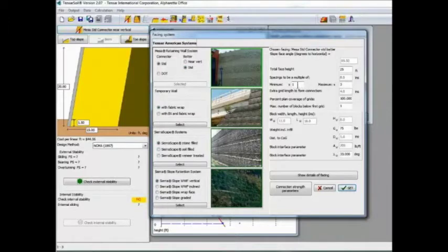You can change the minimum and maximum spacings for the geogrid from 1 times this 8-inch height, and then the maximum could be up to 3 times this 8-inch unit height. Again, the grayed out area would be non-changeable. The areas that are black can be changed in text.